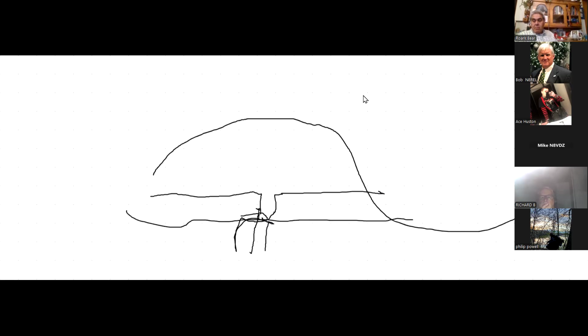It's called a parasitic element because it depends on the power. It's a little longer, and it will reflect. It'll keep the power from going in the back. And the next element, called the director, is a little shorter than the driven element, and that directs it.